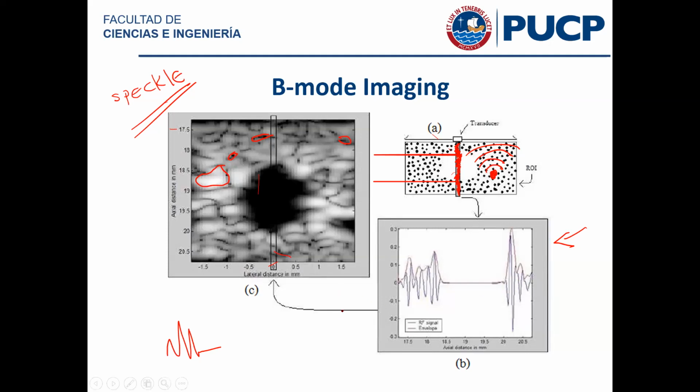Then you move the transducer to a second location and repeat the process, and the same in a third location and a fourth and so on. For every location, you have a new set of echoes that becomes a new column in that B mode image. That's how you construct the image, by moving the transducer, in principle. In practice, you're not going to move anything because that would be completely impractical, but in principle, that's how it would be done.